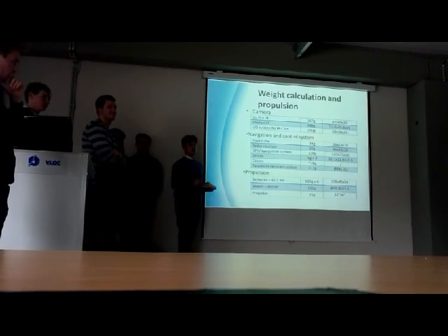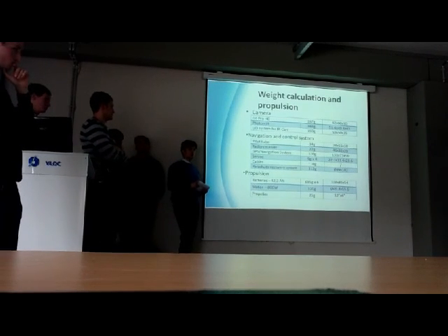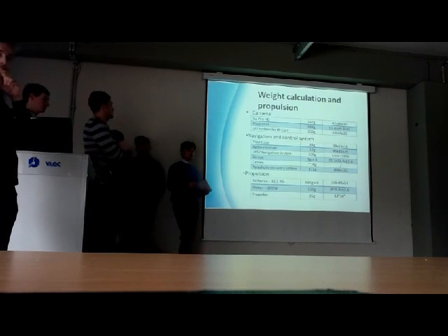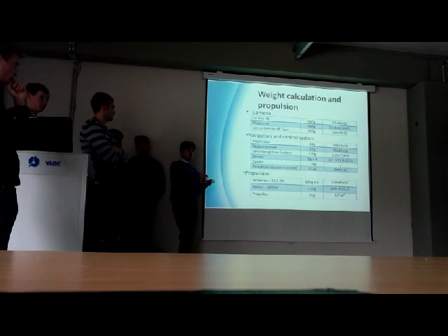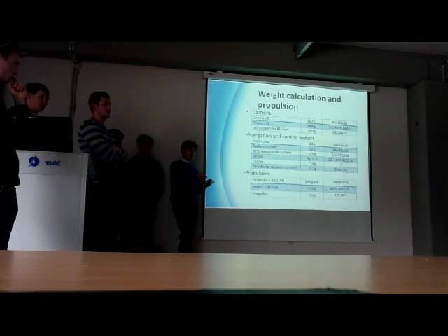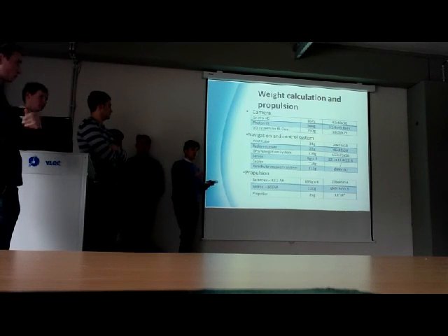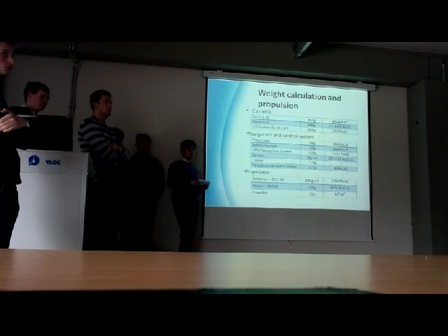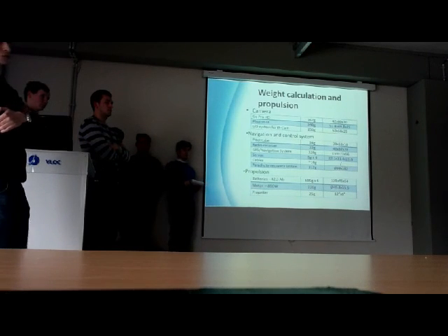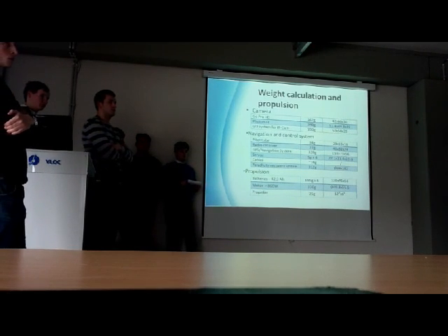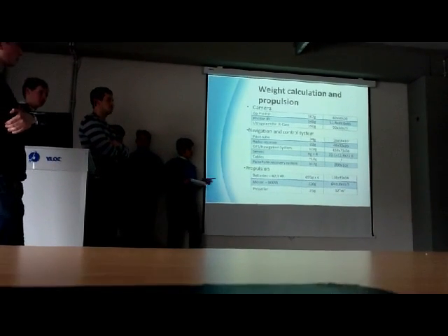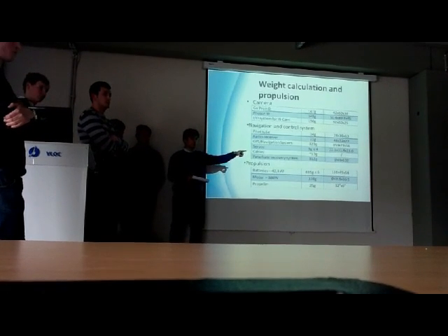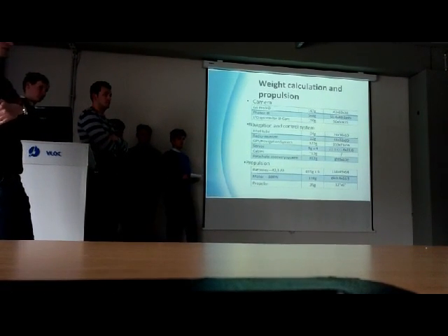I'll show you the only assumption that we do. We have no inner structure. We don't have to calculate the center of gravity due to the presence of an inner structure, only batteries. Yeah, but I'm not talking about the mass center of gravity as a result of the calculation. I'm talking about the center of gravity to have stability and balance in your aircraft. That's what I was talking about. Well, the one you calculate and the one you fly.